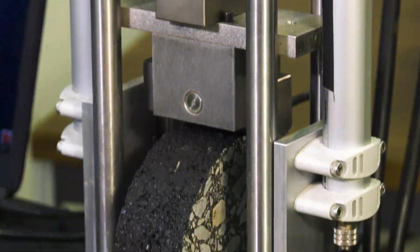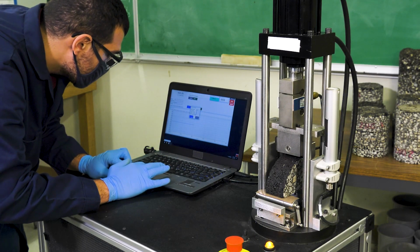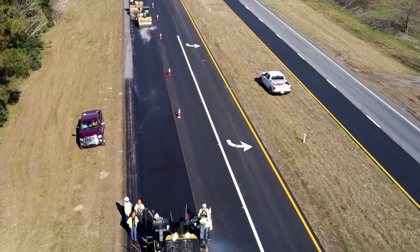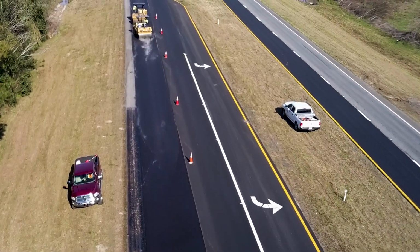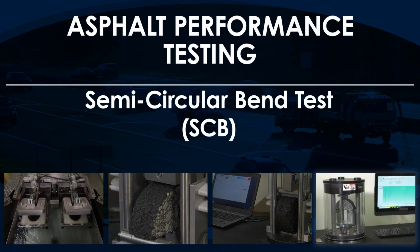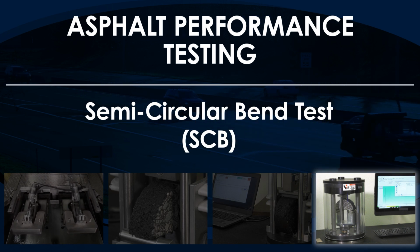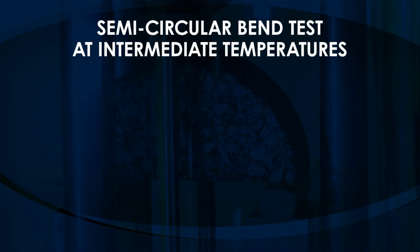Asphalt mixture performance tests help agencies, contractors, and researchers improve asphalt performance and prolong service life of flexible pavements. This video is part of a series on asphalt performance testing and demonstrates the semicircular bend test, or SCB, at intermediate temperatures. The data from this test can be used as a performance indicator to determine an asphalt mixture's cracking resistance at climatic intermediate temperatures.